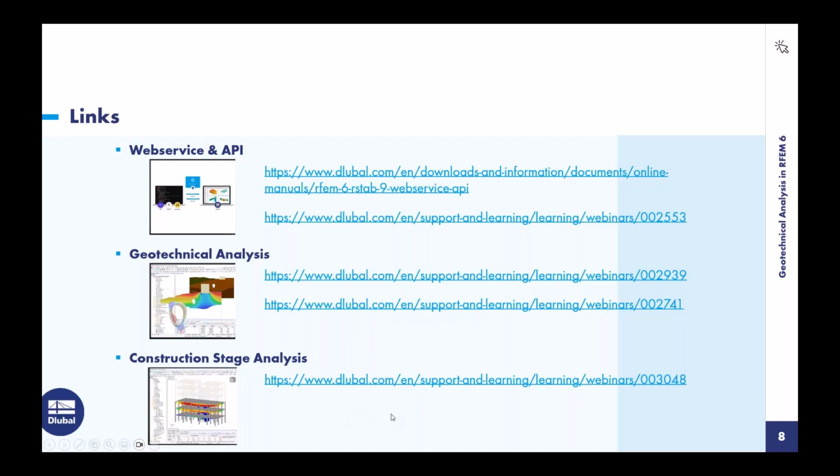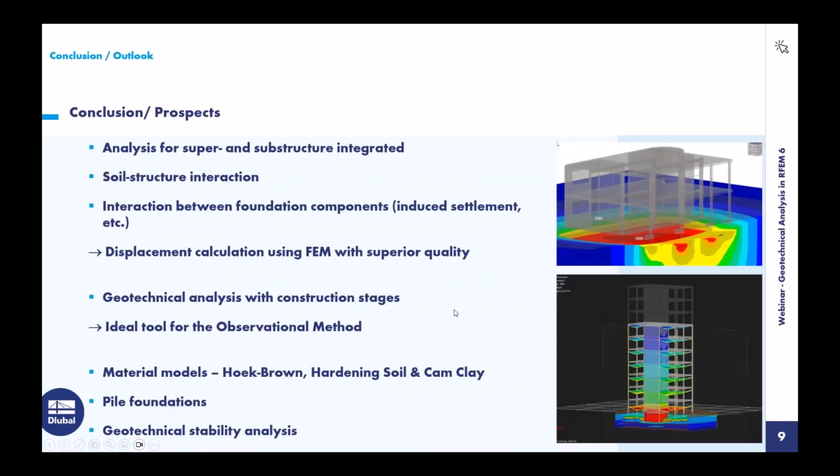As for the higher soil material models, it's quite common to use the construction stage analysis, because you can then more in detail consider the stages of the construction and the loading, and therefore the correct stiffnesses, as we remember the correct stress states and the correct stiffnesses in the soil. So it's connected to our topic. That's enough for this one. Now we come to the final slide.